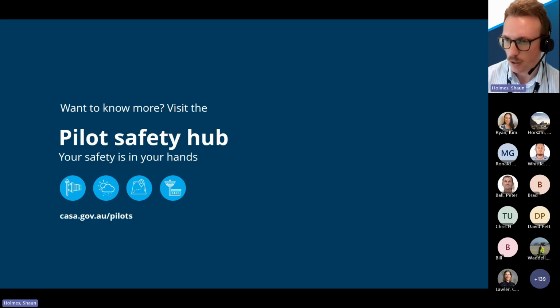Andrew, is a mobile phone an acceptable backup device for a Part 91 private operation? Yes. There are no longer specific screen size requirements. It's a recommendation that it's 200 millimeters diagonally. So if you feel that using a mobile device as a backup is not going to create any additional hazard if your main EFB fails, then that's definitely a suitable option if you'd like to use that.